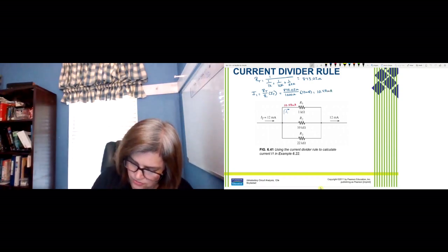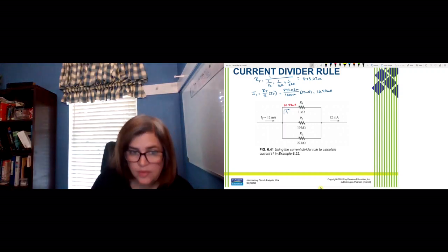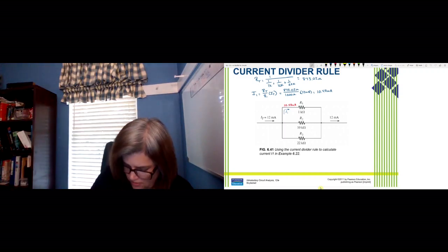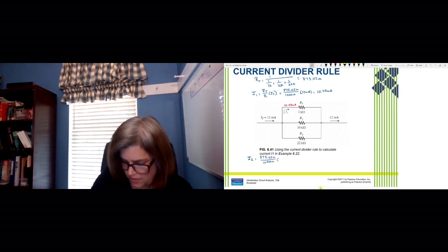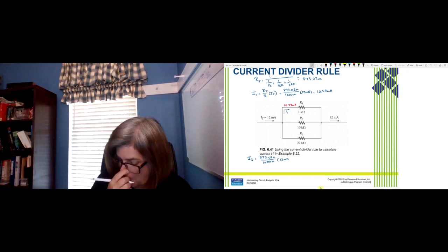We're going to do I2 the same way, maybe underneath here. So we've got, again, 873.02 ohms is RT over 10K times that same 12 milliamps coming in.